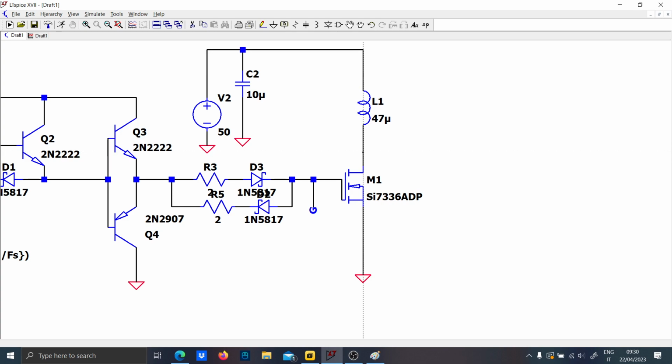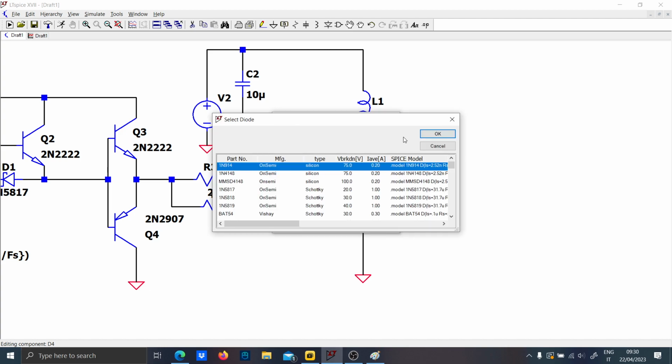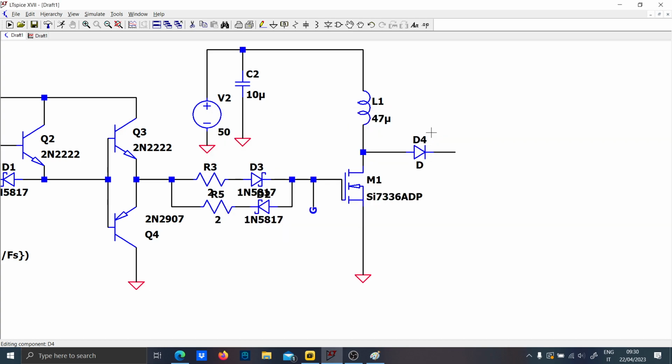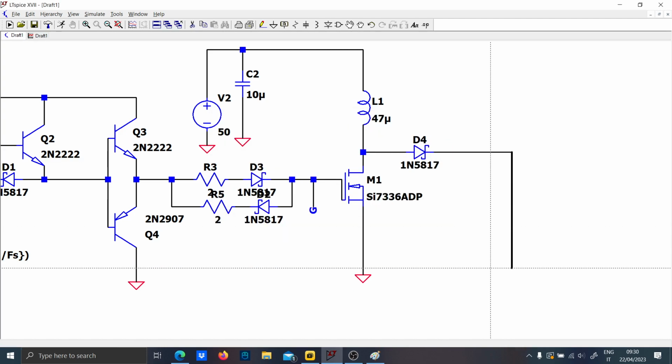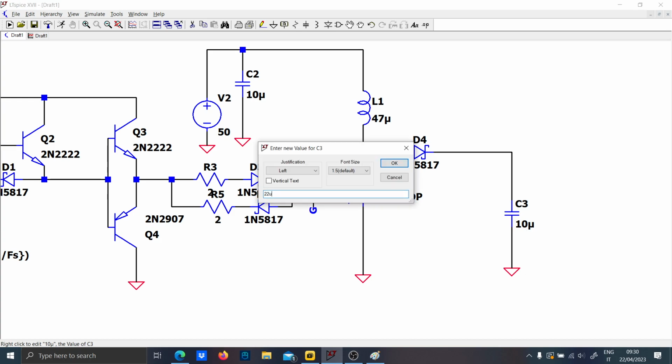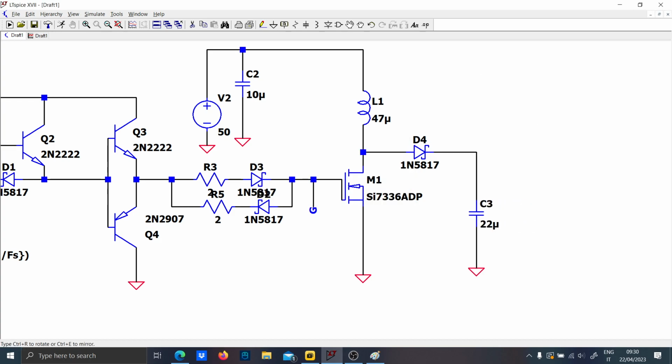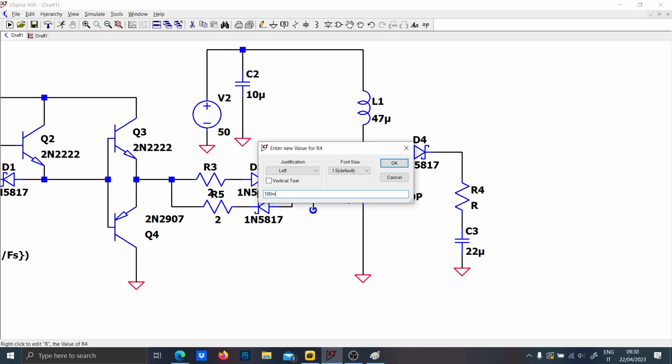So let's connect the diode, the Schottky diode, and let me connect here an output capacitor of 10 micro, maybe a little higher, and let's put also some banks of output capacitors, because you want to reduce the ESR, which will still be present, like for instance 10 milliohms.